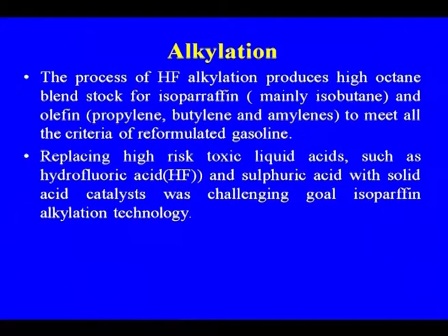Replacing high risk toxic liquid acids such as hydrofluoric acid and sulfuric acid with solid acid catalyst was the challenging goal in isoparaffin alkylation technology, and this has been the major development in the catalyst, the shifting from sulfuric acid to hydrofluoric acid and from hydrofluoric acid to solid acid catalyst.